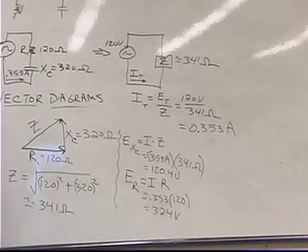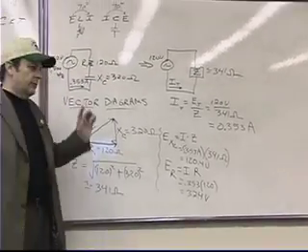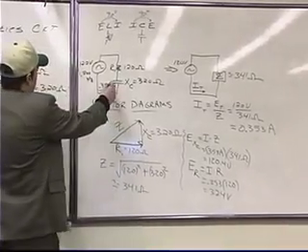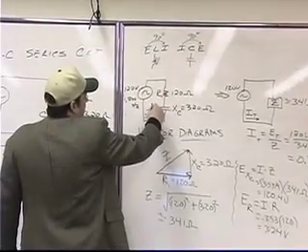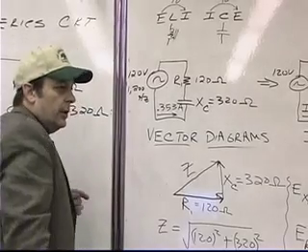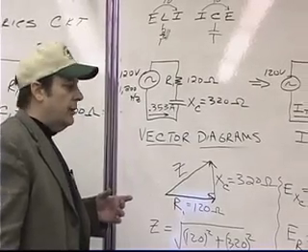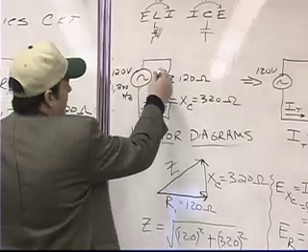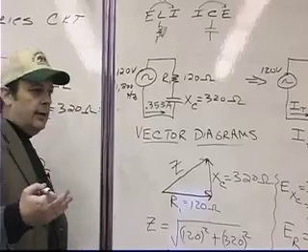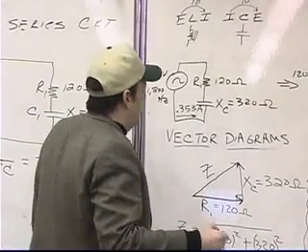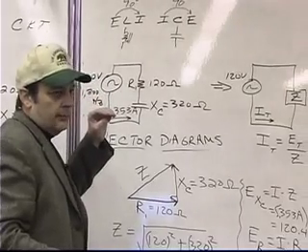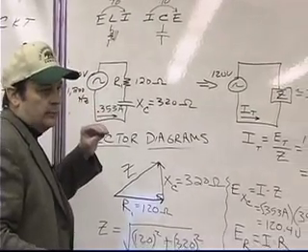Now, one thing that I want you to notice, which is very important in this, is that when we come back to this original circuit right here, and we look at Kirchhoff's voltage law around the closed loop, it still applies. But there's a difference between analyzing DC circuits and analyzing AC circuits. And the difference is that the voltage does not add up algebraically. It adds up vectorially.